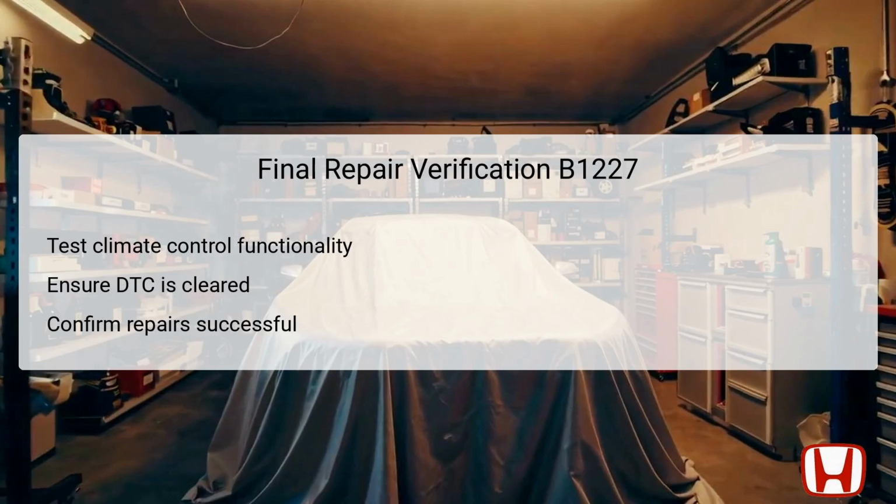Testing should ensure that all climate control features operate effectively, responding correctly to input from the outside air temperature sensor. Additionally, after conducting these tests, you must ensure that the DTC B1227 has been cleared from the system. If the DTC remains, further investigation is warranted. Successful completion of these final verification steps assures that the underlying issues have been corrected and that the climate control system operates as intended, providing comfort and efficiency for the vehicle's occupants.